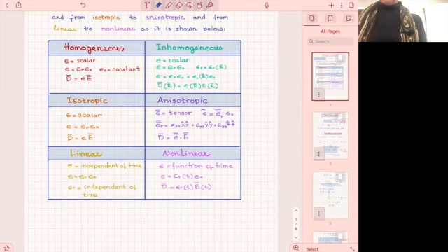You may not see the importance of this now, but if you go to a higher class in electromagnetics, you'll see why it is important, because there are a number of materials that are anisotropic, which means that if I have an electromagnetic field, then along x, E sub x is going to have a different epsilon multiplied with it to find D. Sometimes the relationship between D and E is not a scalar relationship, like multiplying by a constant, but is a tensor product.